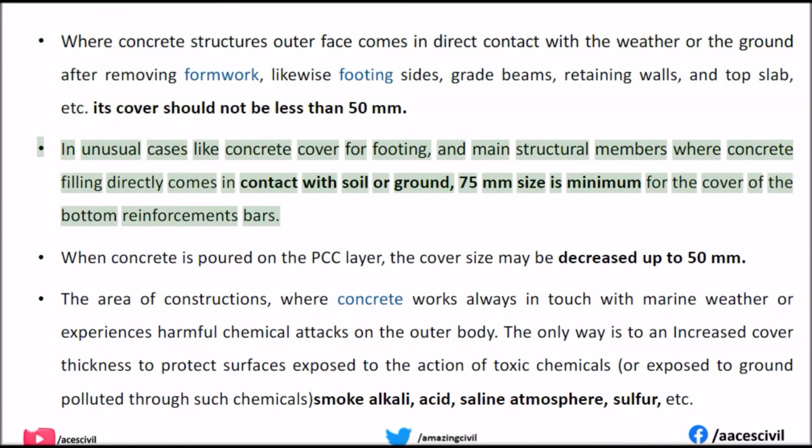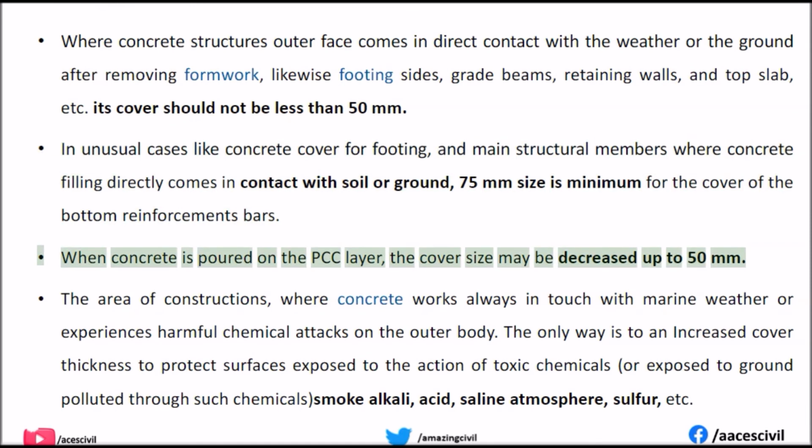In unusual cases like concrete cover for footing, and main structural members where concrete filling directly comes in contact with soil or ground, 75 mm is the minimum cover for the bottom reinforcement bars. When concrete is poured on the PCC layer, the cover size may be decreased to 50 mm.